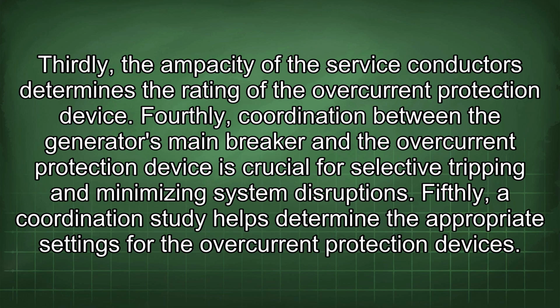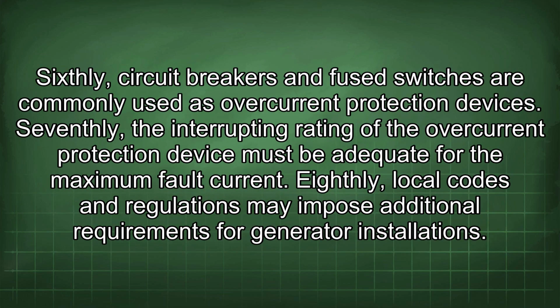disruptions. Fifthly, a coordination study helps determine the appropriate settings for the overcurrent protection devices. Sixthly, circuit breakers and fuse switches are commonly used as overcurrent protection devices. Seventhly, the interrupting rating of the overcurrent protection device must be adequate for the maximum fault current.